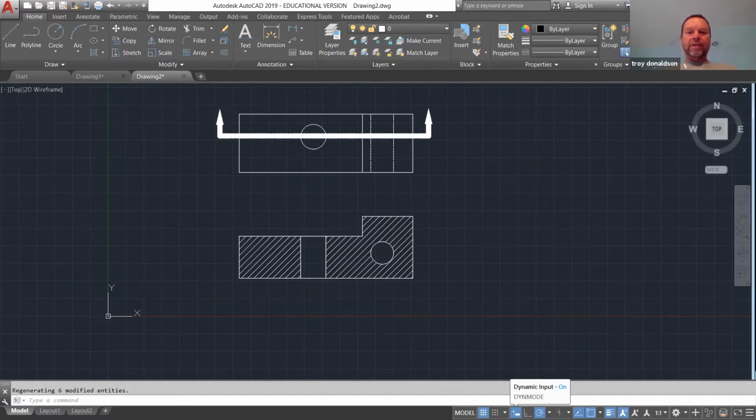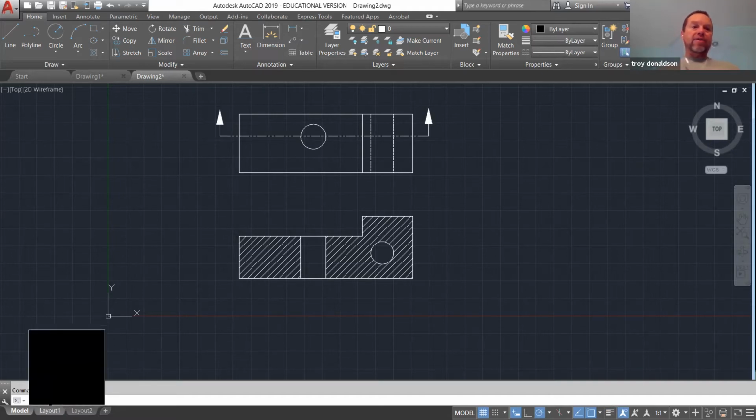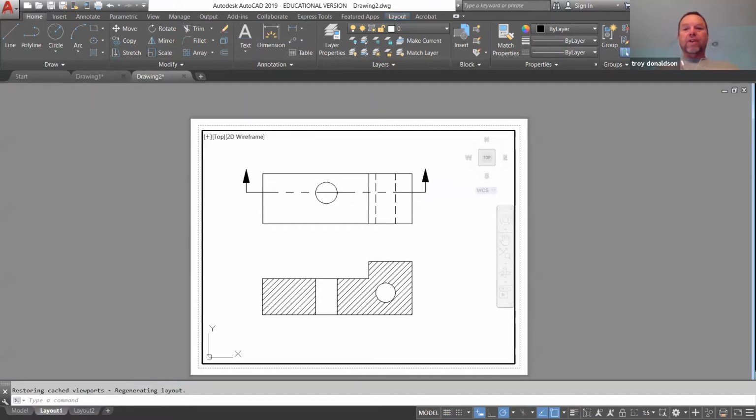That's why there is a line weight button. So you don't show that line weight. You can just see that kind of thing until you get to layout. And once you get into layout, don't forget to hit your line weight button because we do want those things to be nice and thick for our sections, okay? All right, so play with that. It can be a real struggle. So I covered a lot. Feel free to rewind me and go through it again and practice. All right, take care.